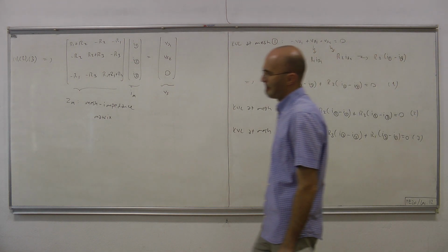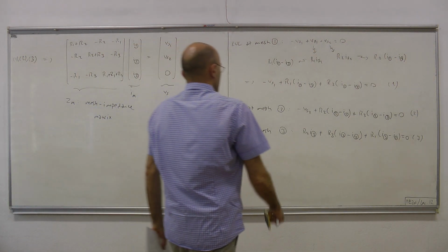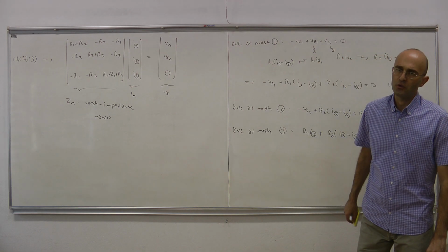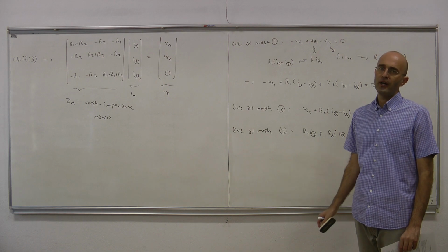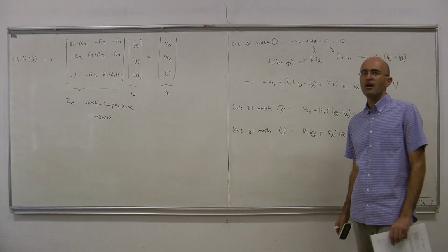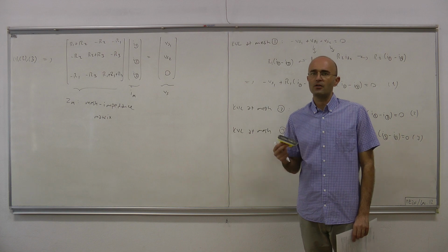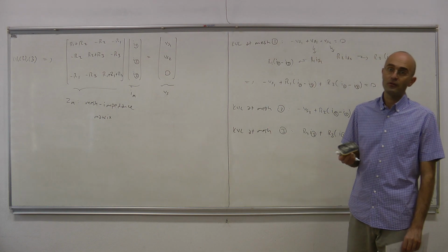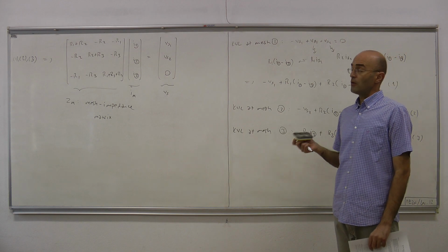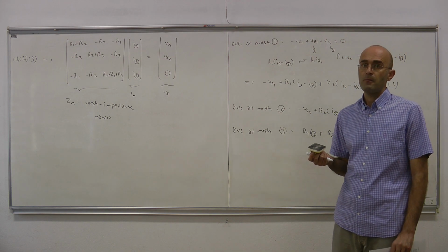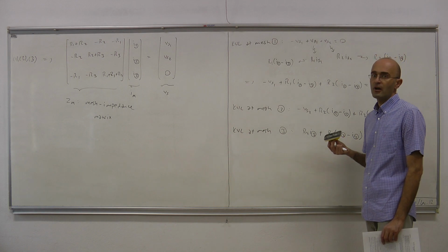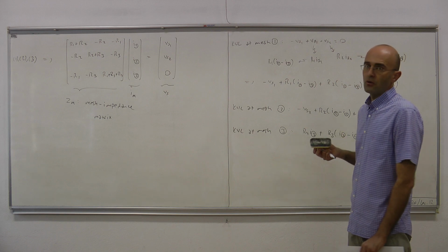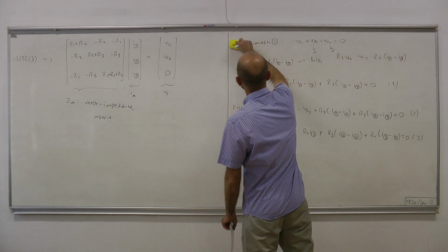Now, in this example, all the sources were voltage sources. And whenever we have voltage sources, we don't have any direct problems writing KVL equations. But whenever we have current sources in our circuit, sometimes it may be difficult, or impossible, to express voltages through them directly in terms of the formulation variables, mesh currents. Therefore, we have to modify the method a little bit. Okay. So we're going to talk about that now.